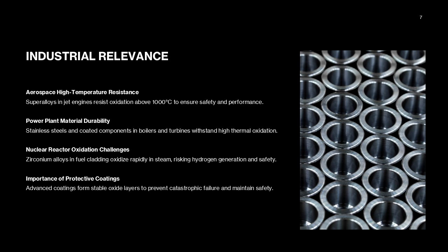thermal loads. Nuclear reactors present unique challenges, as zirconium alloys used for fuel cladding can oxidize rapidly in high-temperature steam, especially during accident conditions, leading to hydrogen generation and safety risks. These applications demand advanced materials and coatings that can form stable, protective oxide layers under severe conditions. Failure to manage oxidation can result in catastrophic equipment failure, costly downtime, and safety hazards.